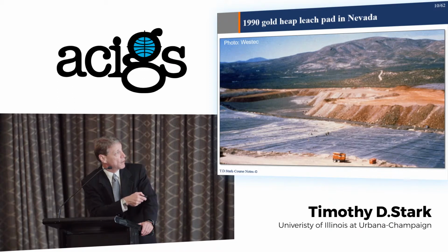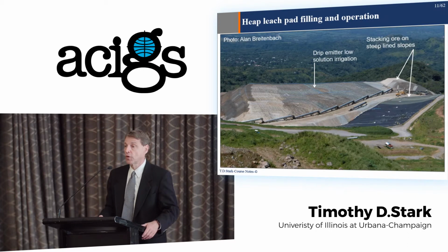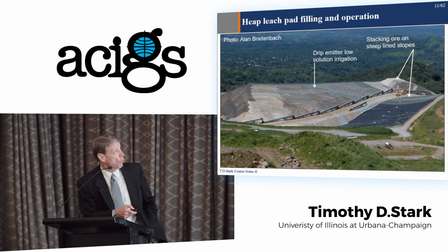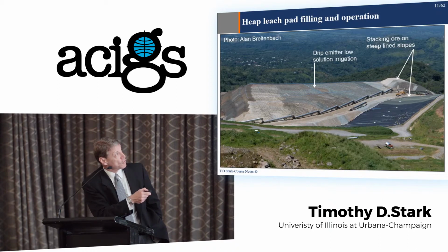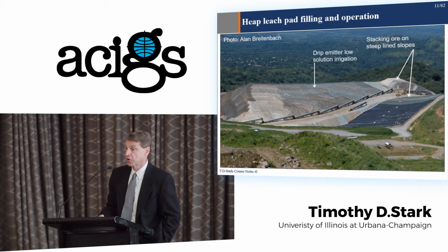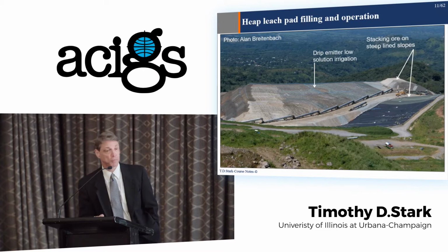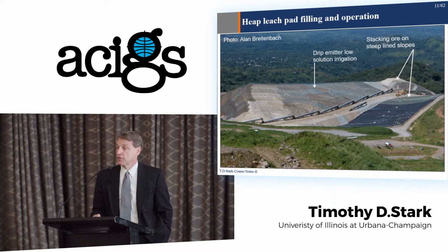Here's a heap leach pad. Here's the geomembrane being installed. Cushion geotextile here, and of course the ore pile right behind it. Here's the full operation. The ore is being stacked in the back and placed on, notice, steep lined slopes, and I'll talk a lot about slope stability in just a minute, but frequently slopes do